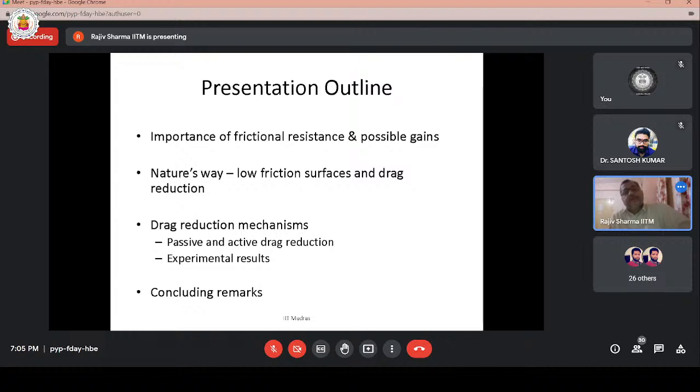the viscous pressure drag. So, drag or resistance will have two components. One is driven by the friction, the Reynolds number. Second is driven more by the Froude number. That's the viscous pressure drag. Frictional drag is dependent upon the surface area and the Reynolds number. Viscous pressure drag depends upon the Froude number and how the structure is paired, how the nose is paired with the middle body, how the middle body is paired with the tail, and whether the body is full or fine, or how the shape optimization has been